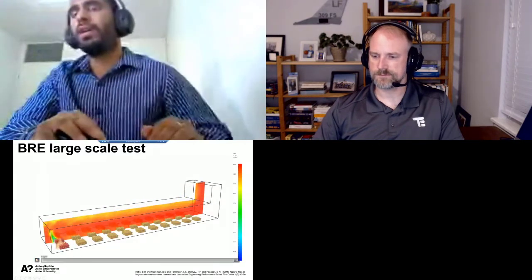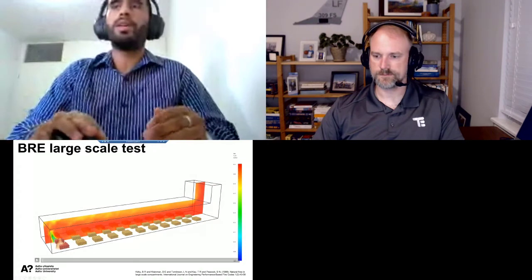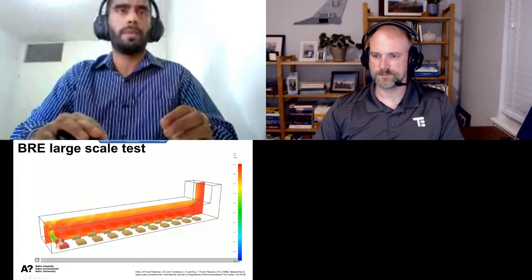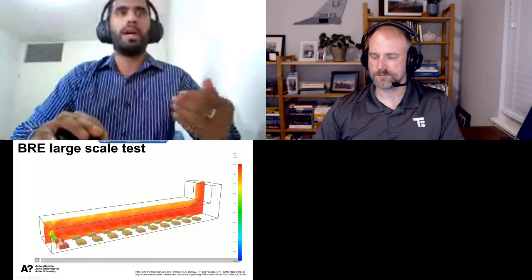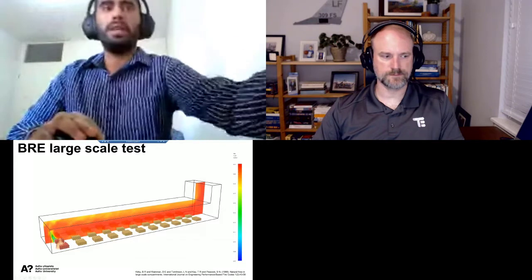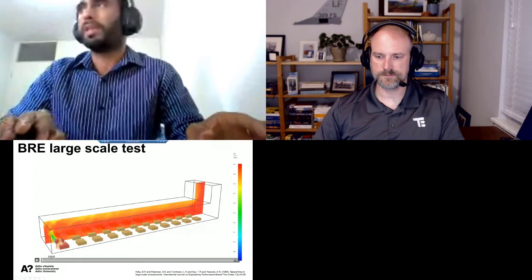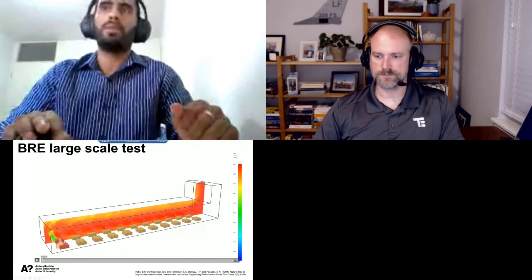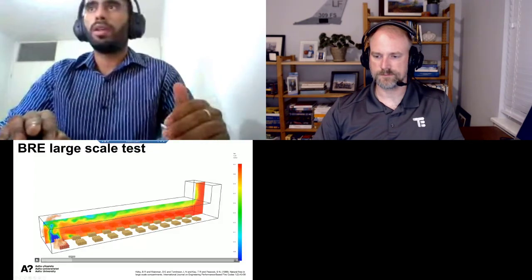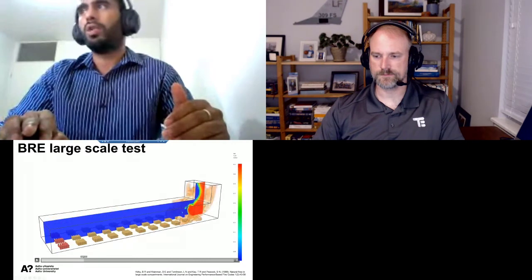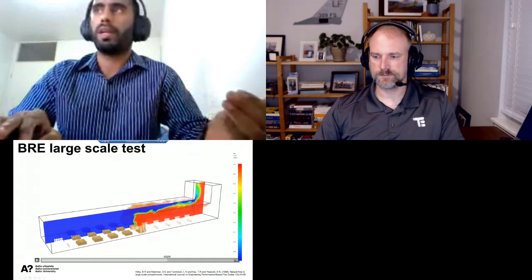So let's see how the whole thing develops. As you can see, initially the fire started at the first row because that was ignited. In the simulation, we modeled the first row with the ignition temperature model. It had an ignition temperature of 300, and it had vents underneath, which acted as the burners. The rest of the wood cribs, which you see in yellow or light brown, are modeled with the single-step pyrolysis. Then, as the oxygen is consumed, there is a rapid spread towards the opening, and then there is a slow backward spread of the fire again.